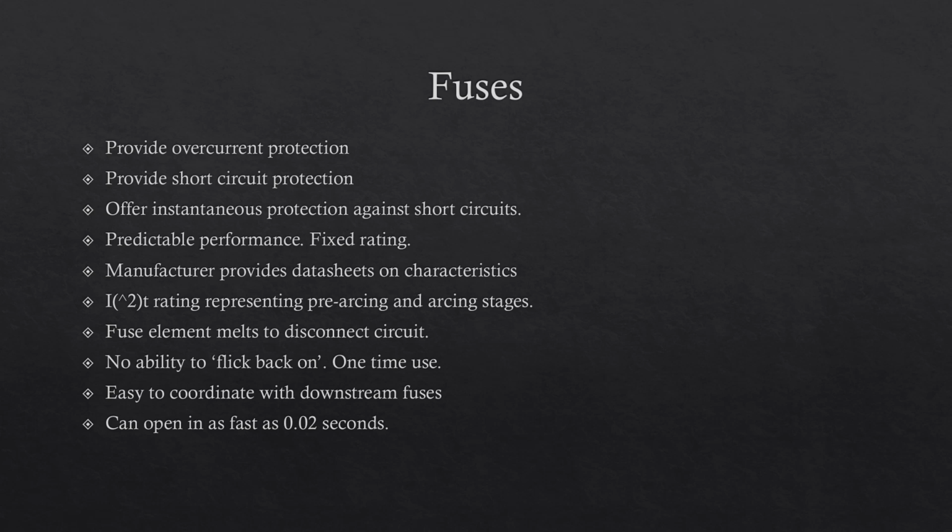Either way, this fuse can detect this current and trip it in a slower time than the next type of fault called a short circuit, where, for example, there has been a cable cut by a contractor, and now there's electricity flowing to the ground, trying to get back to its source. Another fault occurred, and with that, an extremely high current is flowing. The fuse will almost instantly disconnect it.